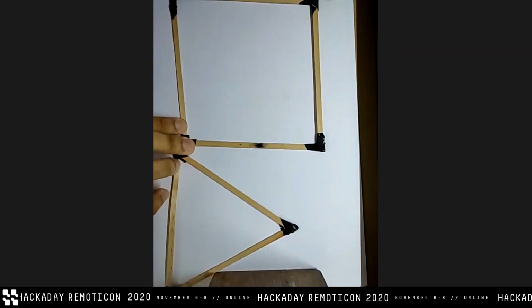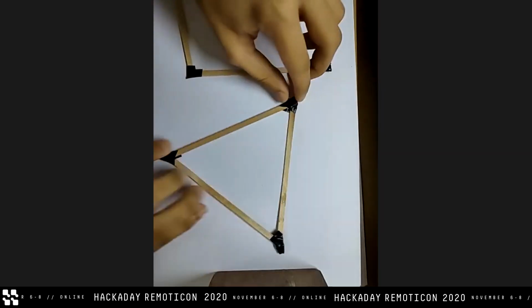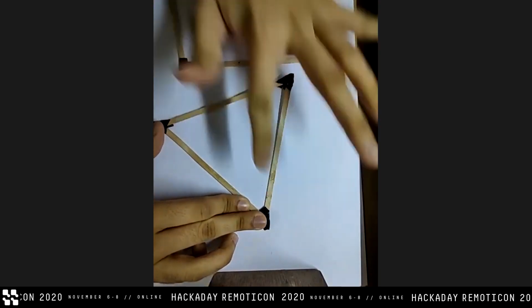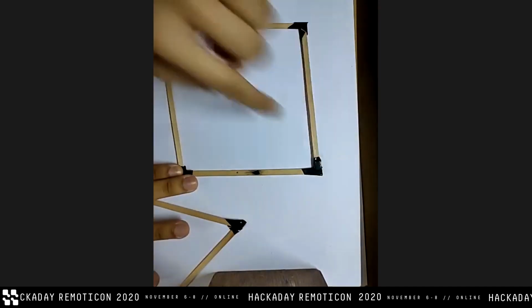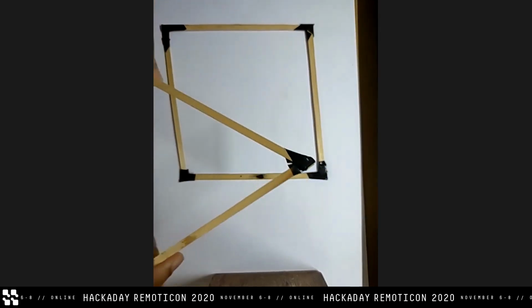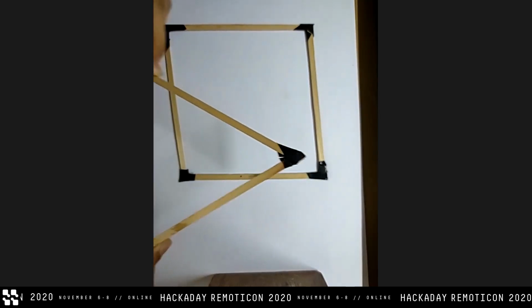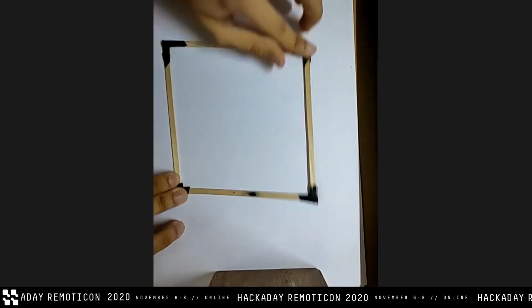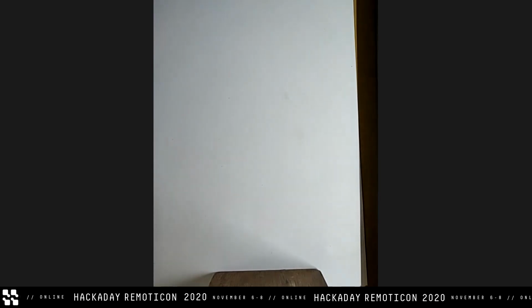You'll see with this, when I push on it, the whole thing can turn. Whereas over here, when I push on it, nothing really happens. All of the force is being directed along the beams. Whereas over here, it can be directed along one of the diagonals where there is no beam. That's why the triangle is always the strongest shape, because I can't make any connections to the corners without it crossing a beam. It really comes down to your shearing versus compressing, and that's something we're going to look at now.